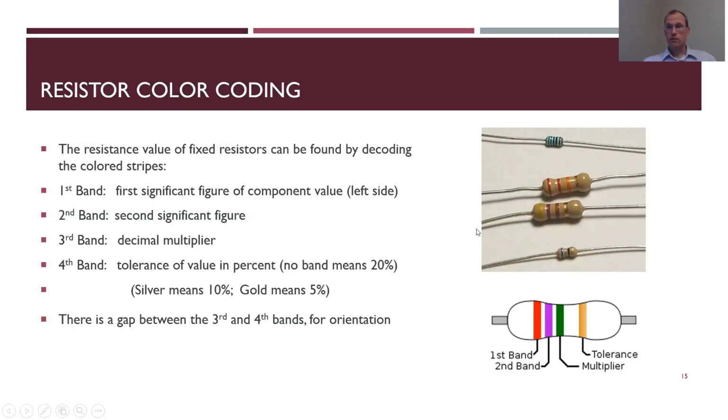So for your resistors, you can see many of them look the same. Here's a blue carbon film one, some beigeish metal film ones. Generally they all look the same other than their size. Based on the length and cross-sectional area, generally your bigger ones are your smaller values. So these guys have probably a lower resistance than this little guy down here, just based on the cross-sectional area. Even though the length is smaller as well, the cross-sectional area is a lot smaller. So I would guess this guy is probably 100 times the resistance of these guys, just guessing.